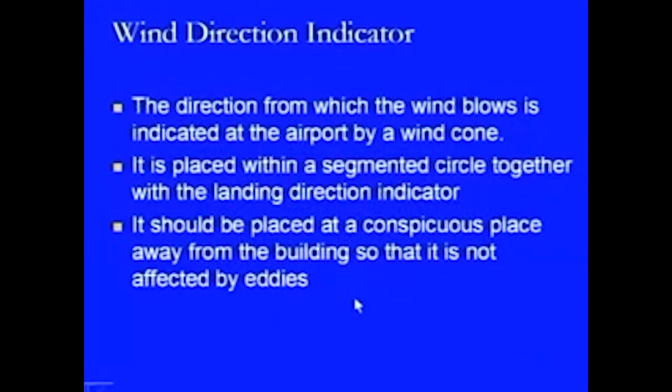Then it should be placed at a conspicuous place away from the buildings, so that it is not affected by eddies. If heavy wind is blowing and it is very near to the terminal buildings, then eddies will form, and in that case it will not be useful to the pilot to understand the behavior of the wind.